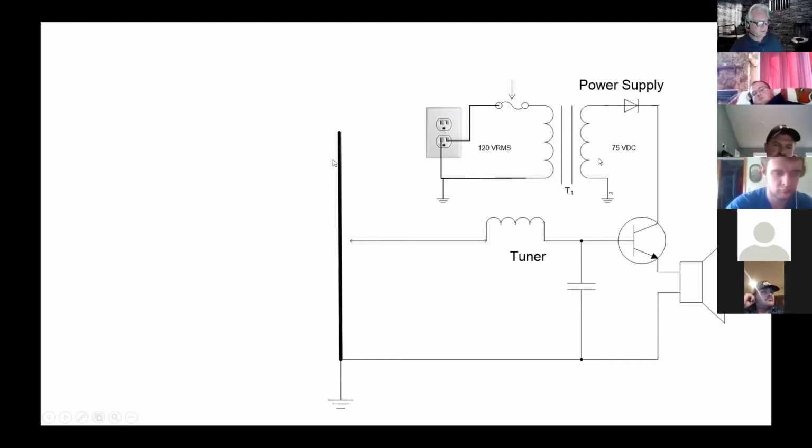So again, I've got an amplifier. The amplifier, we've already learned about power supplies. Here's my primary voltage, my secondary voltage. I'm rectifying it. For simplicity, I just use a half wave rectifier. Ideally, we would have a full wave with filtering and regulation, but you see we've got AC to DC. I've got a DC power supply supplying a lot of current to my speaker, but that current's being regulated by a small filtered signal coming from electromagnetic radiation from a radio station. That's all I've got.